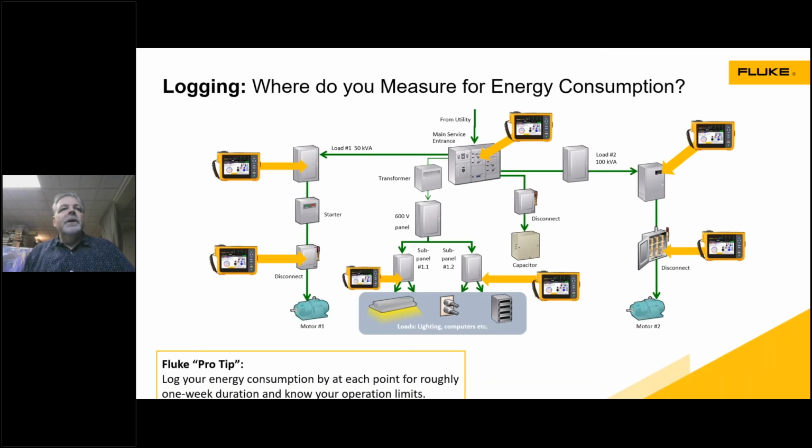Okay, let's talk about logging. Where do I actually measure energy consumption? At the top of the arrow here, usually as the power comes into our system, we'll want to measure what's actually happening to get an overview of what all of our power is. And then you'll want to move your logger, they're portable, battery operated, down into a load, either side of your different loads, down through into individual pieces of equipment.